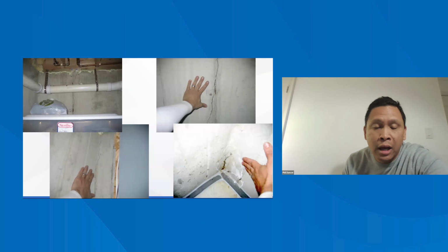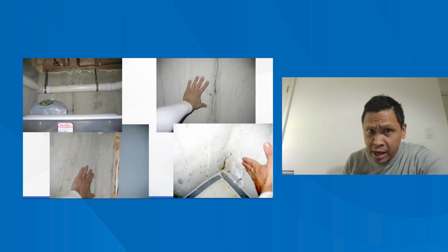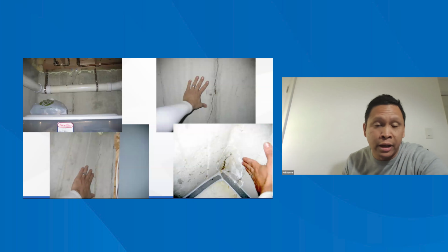So if the basement is finished with drywall, there's no way to be able to see that. That's why home inspections are limited to being visual in nature. It's not reasonable to ask us to discover a latent defect, meaning it's concealed. But it's important, if you are helping a family do a pre-drywall inspection, to do your best to see if the crack is transitioning all the way through the wall.